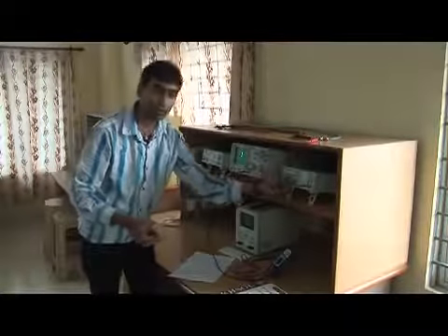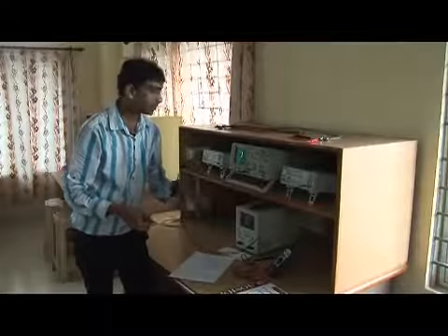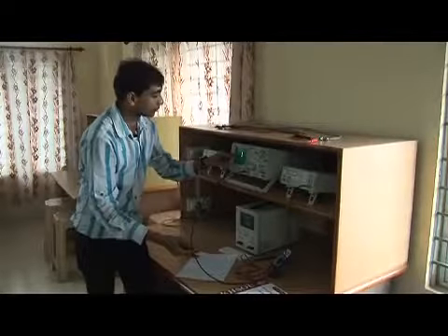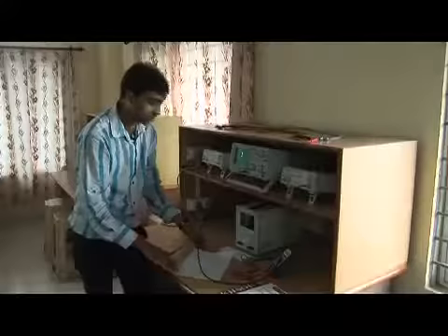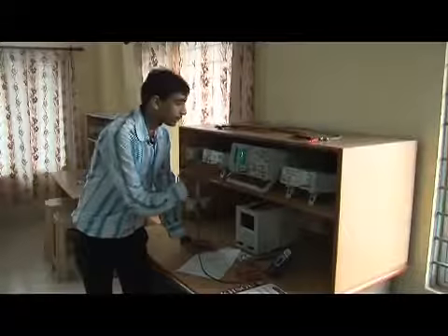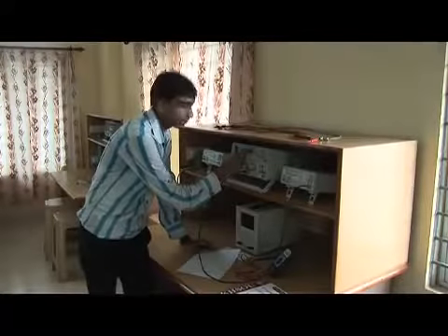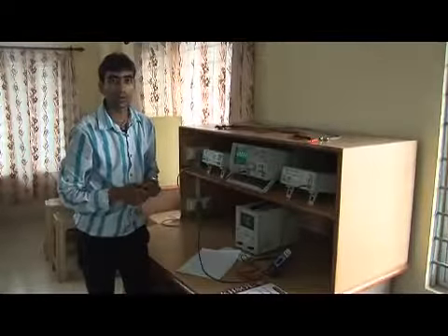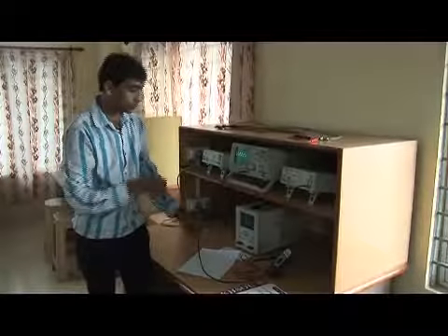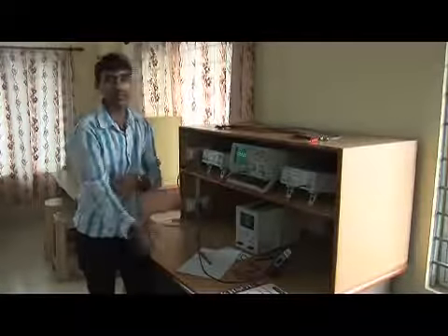So exactly 2 volt is not coming, a small error has crept in here, and 1.9 volt is coming. So this is how we calculate the amplitude. Now moving to the next parameter, I am releasing this x1. We are moving into how to calculate the frequency. To calculate the frequency, we should know the time period.